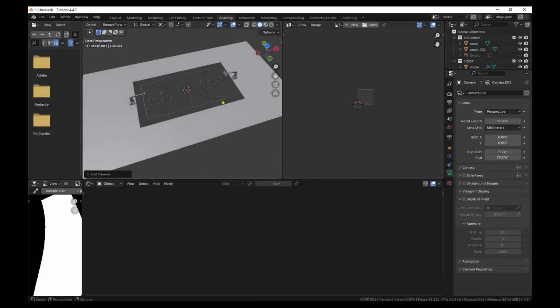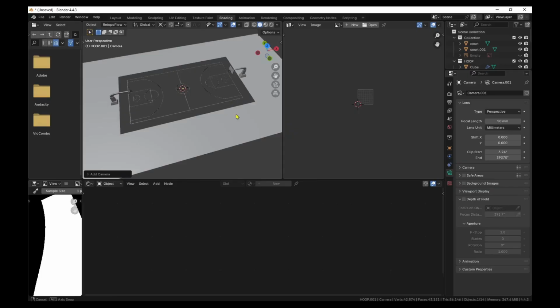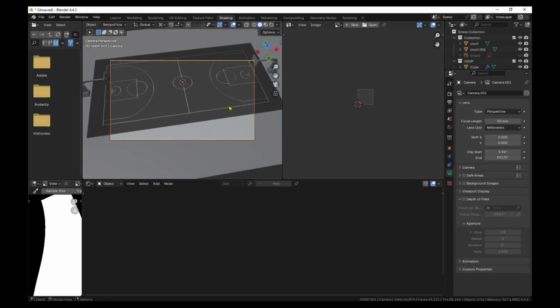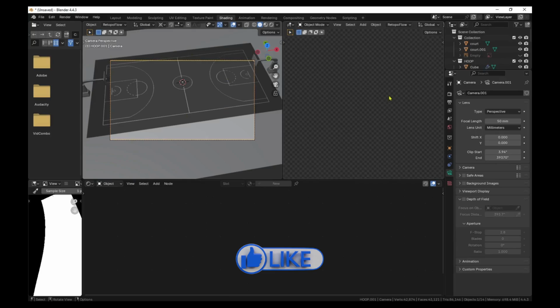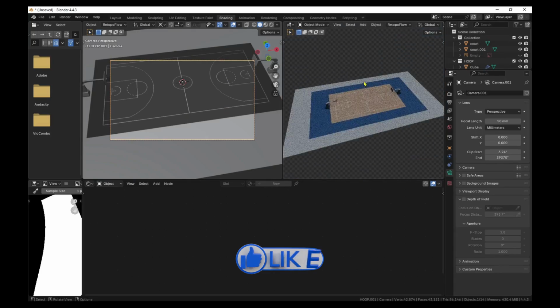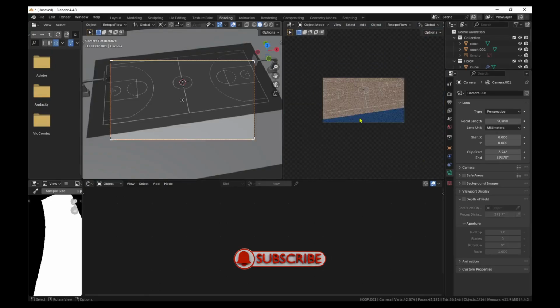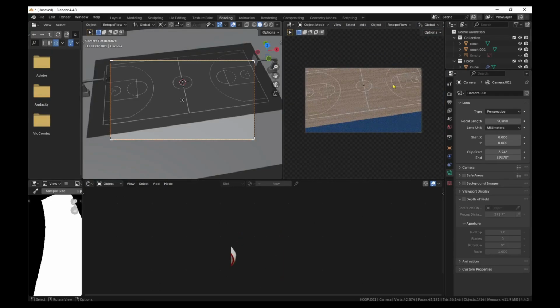So you can preview this scene like this and then hold down your Control Alt key and then numpad 0 to capture our view that we have. So now we're in the camera mode. So let's change this to the 3D viewport and then let's view the camera over here. And we don't need to be rendering all this here. So what we need to do is Control B and then draw across this to view only the things that we can see in the camera. So let's also disable this 3D scene here.